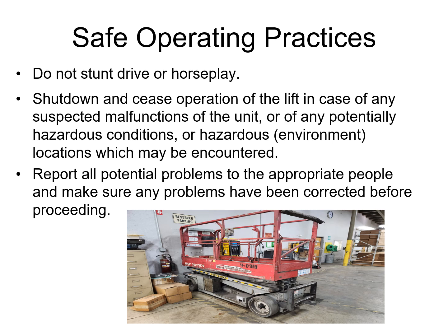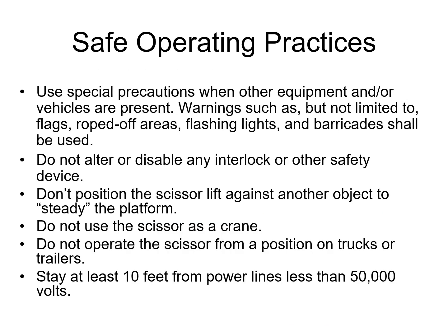Safe operating practices continued. Do not stunt drive or conduct horseplay. Shut down or cease operation of the lift in case of any suspected malfunctions of the unit or of any potential hazardous conditions or hazardous environmental locations which may be encountered. Report all potential problems to the appropriate people and make sure any problems have been corrected before proceeding.